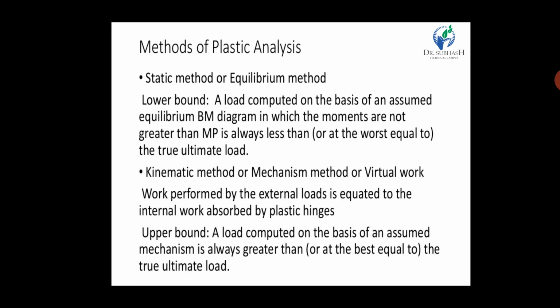Now, methods of plastic analysis. The first one is the static method, or equilibrium method. The lower bound: a load computed on the basis of an assumed equilibrium bending moment diagram in which moments are not greater than Mp is always less than or at worst equal to the true ultimate load.